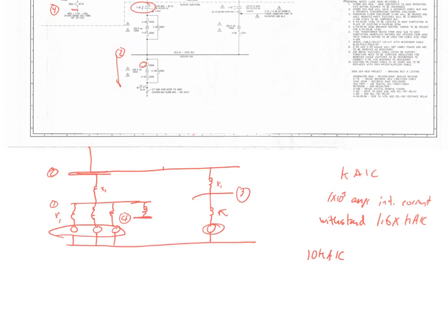What happens when you get sand really hot? It turns to glass. They have a bimetallic element that goes through some sand. As this element heats up, it converts that sand into glass, and then it changes the resistance to super high values. So it knocks the fault current down because you've got glass.